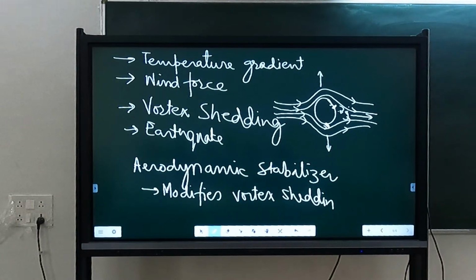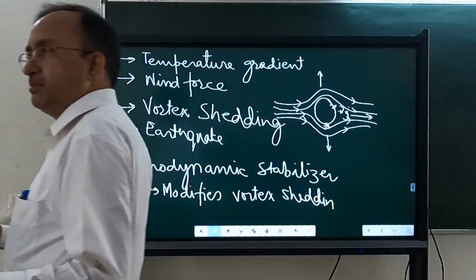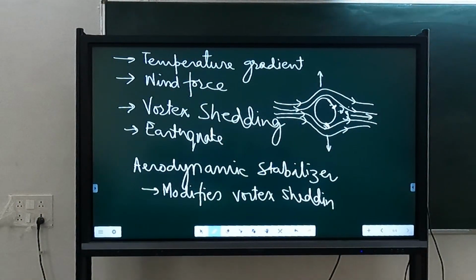Right? Some of the people claim that the Morbi bridge, which collapsed, collapsed because people were trying to shake it. So if you are causing vibrations with the frequency of the bridge, the response will go on building.